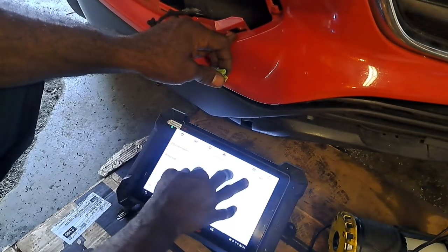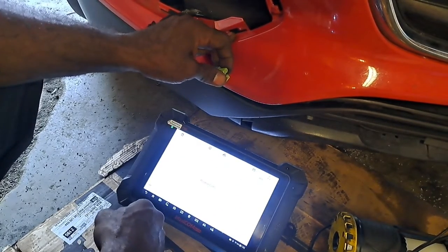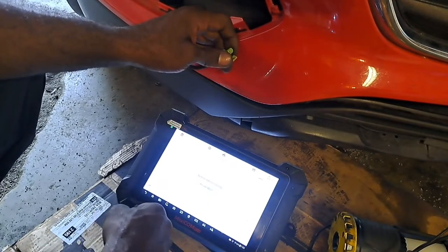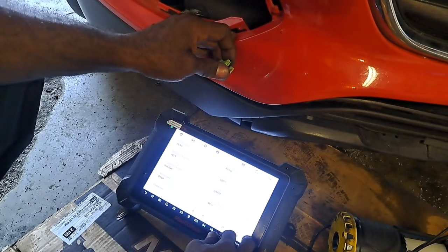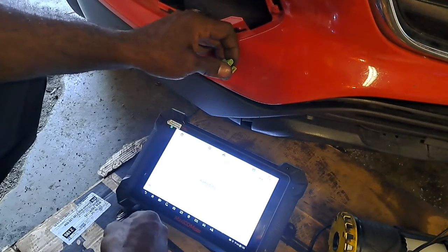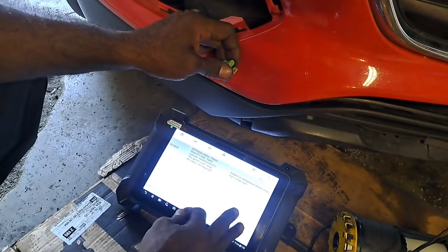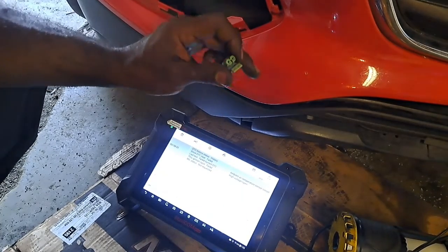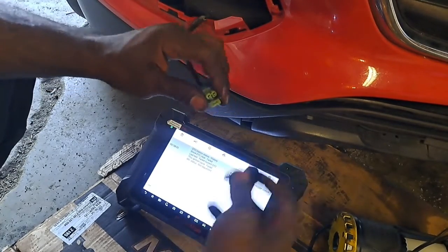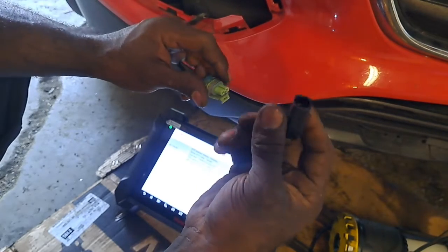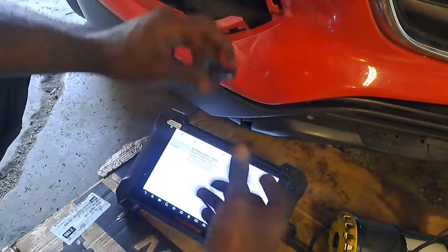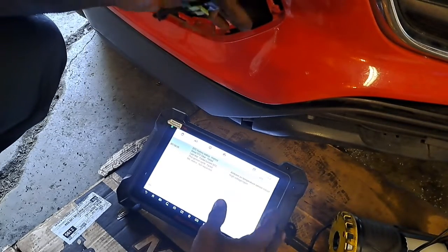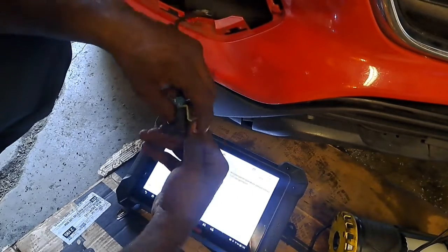Let's go to trouble codes. No fault codes. Should have an open circuit code. B0158. So now I got high voltage versus short. So it needs to see very specific resistance, and we might just have an issue with the sensor now. So we have continuity because it registered as the short code.